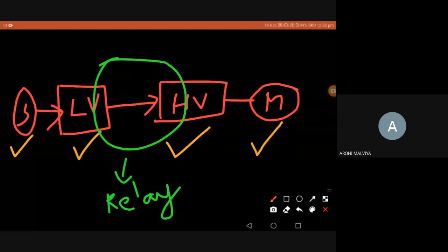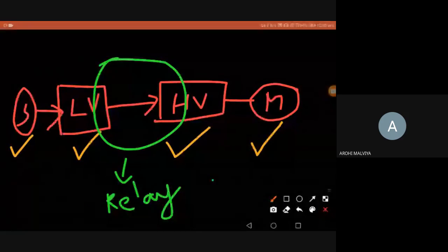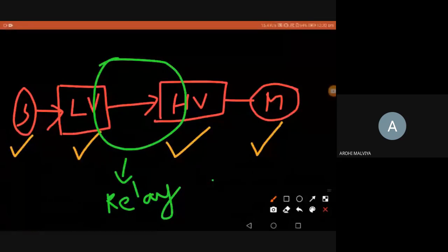If you want to define a relay, you can say relays are switches that open and close circuits electromechanically or electrically. The transistor we already discussed is also an electronic relay, an on off switch based on some conditions, between two points. So a transistor is an electronic relay, but an electromechanical relay also exists. Electromechanical relays work on the principle of electromagnetism and electromechanical motion, even thermal.